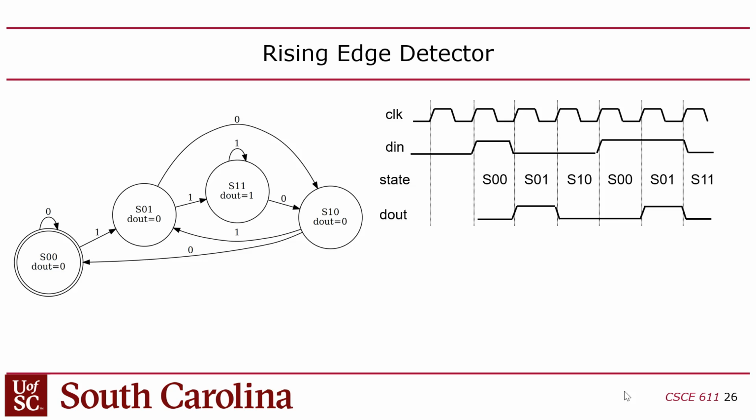Okay. There was something else. Oh, yeah, notice too, I've got nothing in these first 2 cycles, right? Because I don't have a reset. I didn't reset it in here. So I don't know what the state is. Basically, because I have 2 bits of state, and I don't know where I'm starting, I don't know what the initial condition is, right?